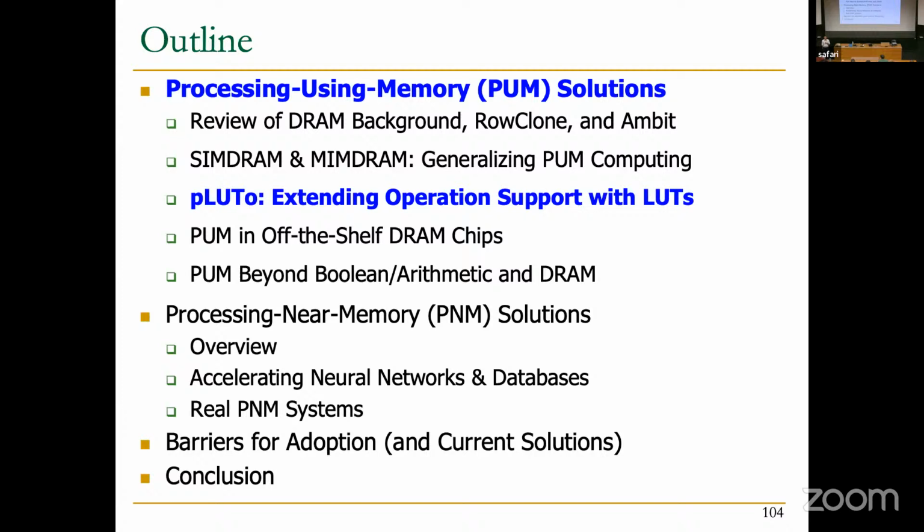If you put some MESI protocols into the memory controller or into the DRAMs themselves, you can offload some of the atomic operations into the memory itself if they are not hit in the level 2 or level 3 caches. So have you done some research in those domains?